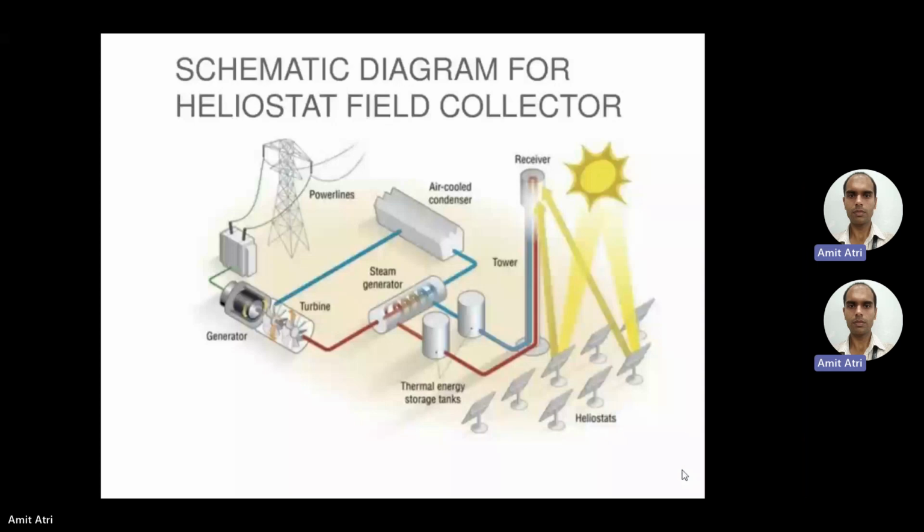So they are nearly flat mirrors that collect and concentrate the solar energy on a tower mounted receiver located 100 to 1000 meters distant. Okay, so such a large distance is there and sunlight is traveling. That's why the efficiency is increased. To maintain the sun's image on the solar receiver, heliostats track the sun throughout the day. Mostly all of these types of collectors, they are tracking the sun so as to obtain maximum efficiency.